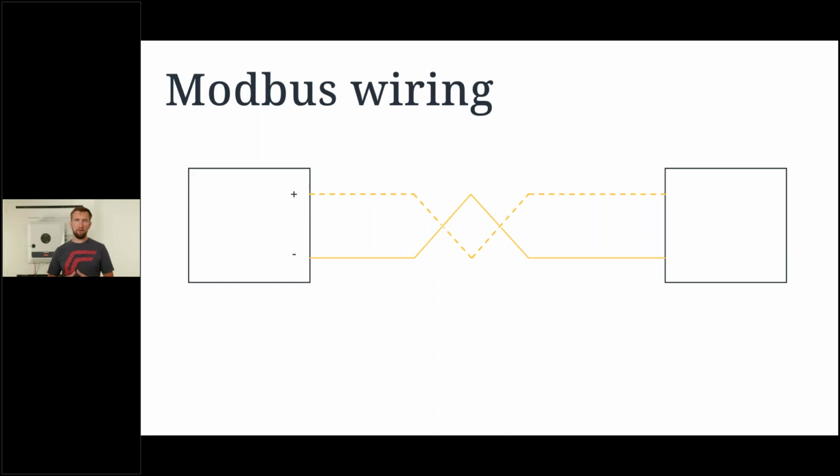The core component is two cables that run parallel to each other. They're twisted, and we have a plus and a minus data. Now on this line, we have equal but opposite signals that are sent, and then at the other end, they're analyzed to make sure that they match. So by using these two cables together, this plus and this minus, we get a good, strong offset signal. The fact that they're twisted is also going to be important because that gives us additional shielding against interference and we can't get mixed up.